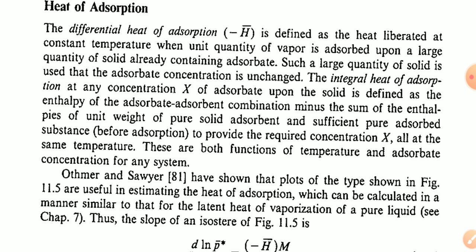The integral heat of adsorption at any concentration X of adsorbate upon this solid is defined as the enthalpy of the adsorbate and adsorbent combination minus the sum of the enthalpies of unit weight of pure solid adsorbent and sufficient pure adsorbate substance before adsorption to provide the required concentration X, all at the same temperature.